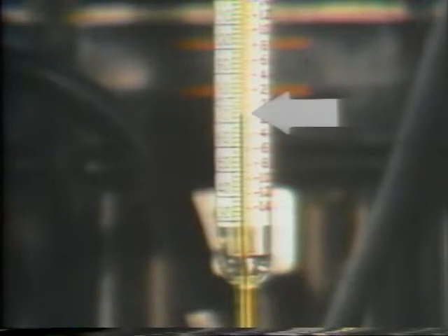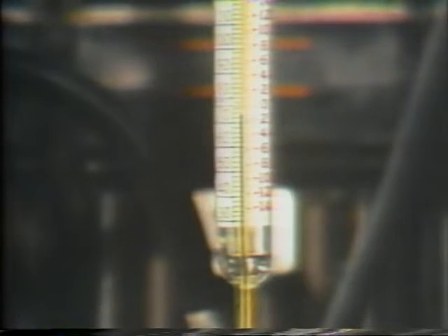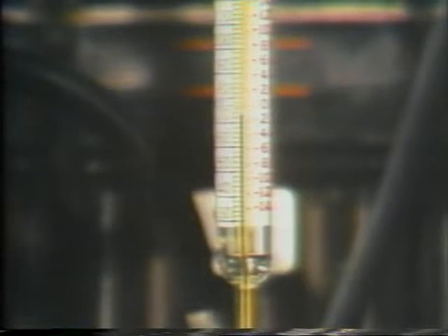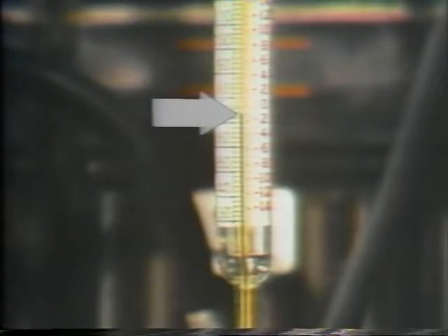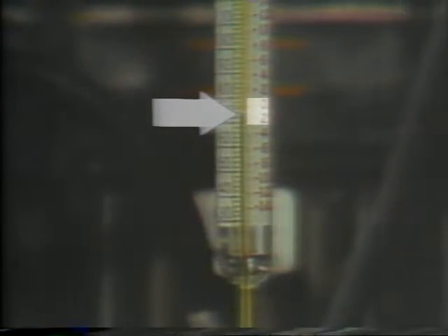The thermometer on this pilot cell shows a temperature of 73 degrees Fahrenheit, approximately 4 degrees colder than the base temperature of 77 degrees. The scale on the right-hand side of the thermometer indicates the specific gravity correction factors for temperatures above or below 77 degrees. This temperature is halfway between 0 and -2 on the scale. The correction factor is -1.